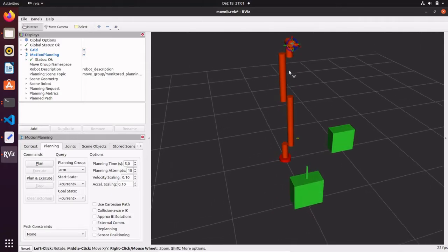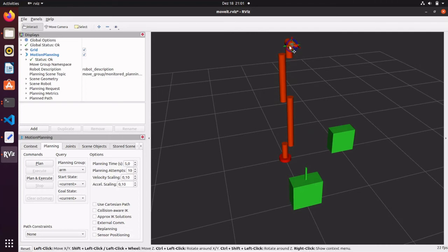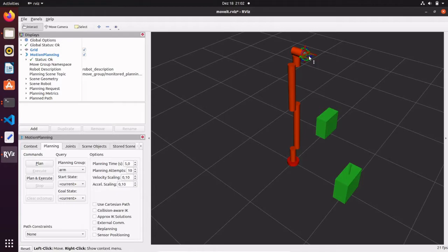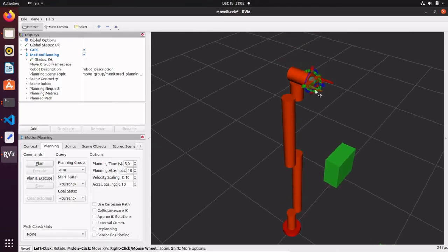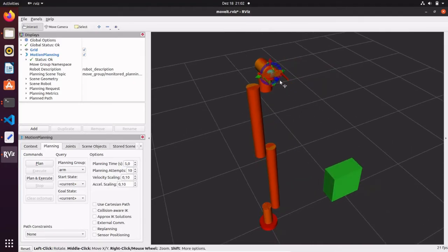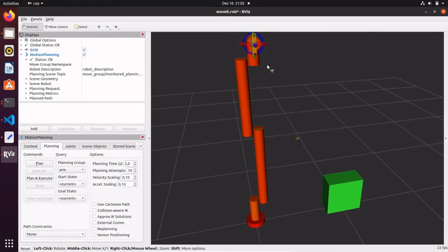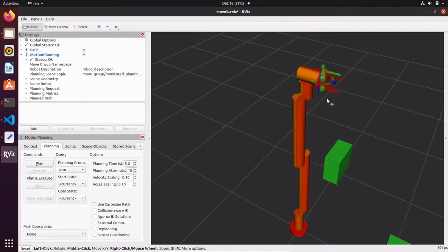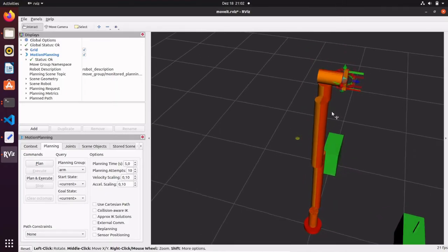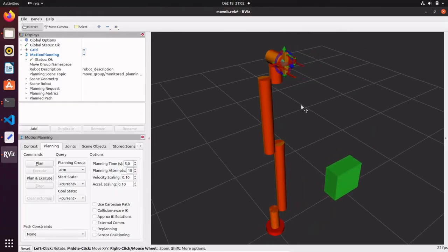So the most important thing to bear in mind is the orientation we are going to select by choosing the roll, pitch, yaw angles. The blue is the axis of rotation that determines the roll, the green will be the pitch, and the red will be the yaw. Basically, what I'm going to code as orientation of the TCP will be a roll rotation of a quarter of rotation and a quarter of rotation of the pitch angle, so through the green axis.